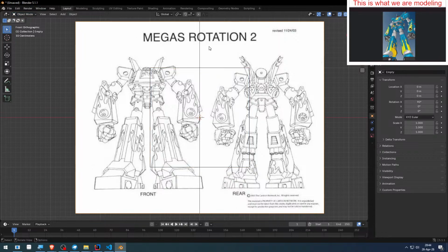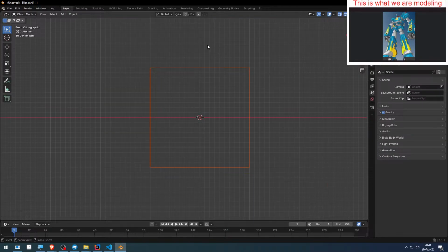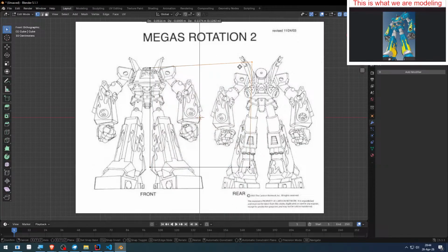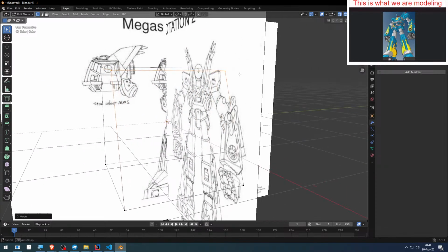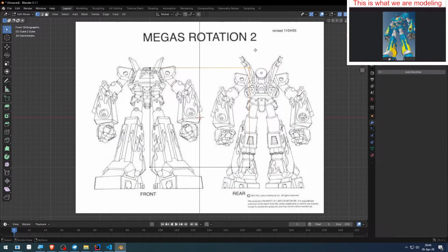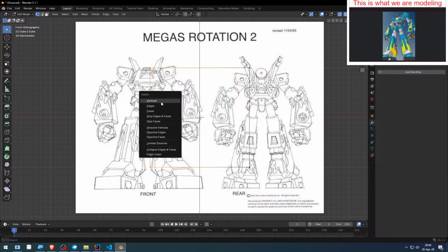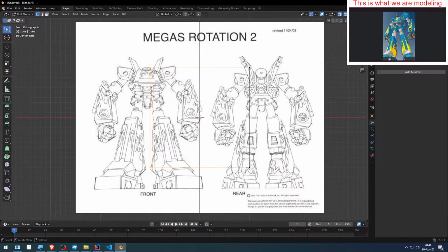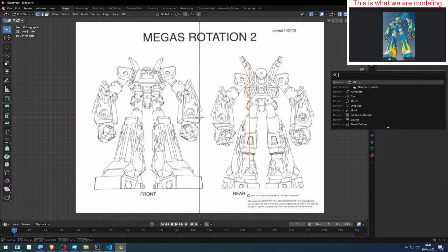Oh, this is object mode. I need to go in edit mode. This is the cube. Yeah, now we're in edit mode. Now I can move this. And I'm capturing the one behind. Sure. But I really need to delete them. Thanks, Lucas. I really need to delete these vertices. Yeah, and now I'll enable the mirror modifier.